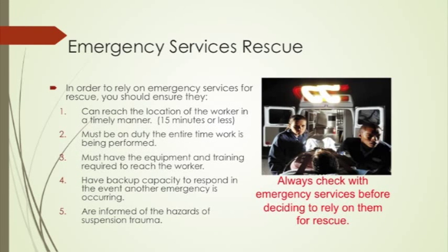Always check with emergency services before deciding to rely on them for rescue. In order to rely on emergency services for rescue, you should ensure that they can reach the location of the worker in a timely manner of 15 minutes or less. They must also be on duty the entire time work is being performed and must have the equipment and training required to reach the worker. There should be a backup in the event another emergency is occurring. Emergency services must understand the hazards of suspension trauma.